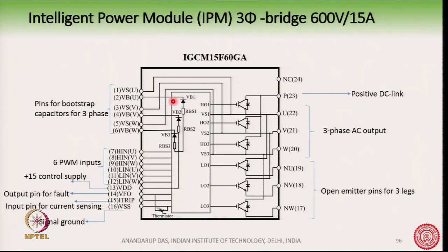Then you apply the PWM pulses to these 6 devices. The gate driver is inside, so you just apply the PWM input from the microcontroller.